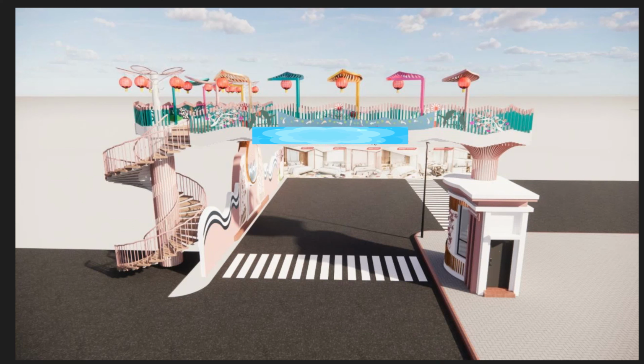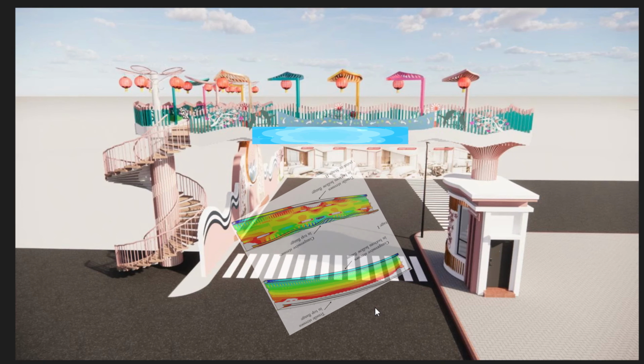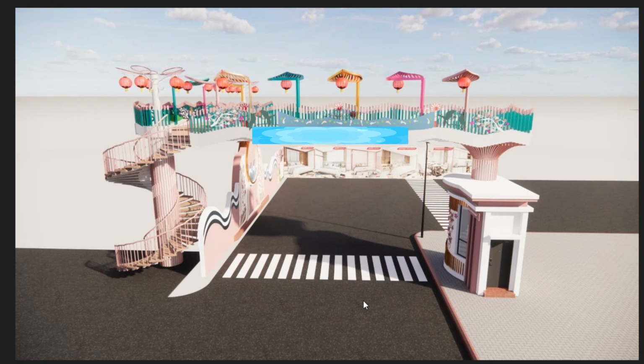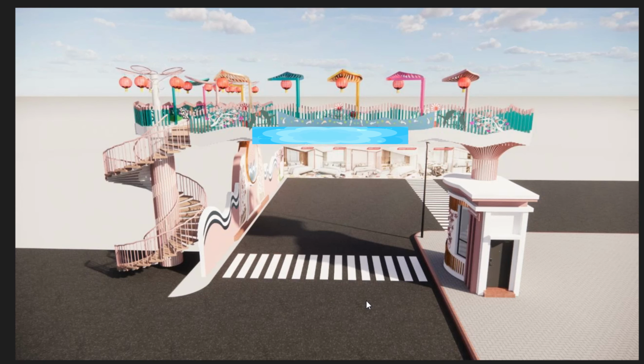3D architectural plan. Now let me ask you one question. How do we design steel composite walkway? What is the design control on the project? The ultimate limit state, the strength of the section, the deflection, or the local buckling or lateral torsional buckling that control this design. Now let's jump into the deep about this tutorial. You will know how to design and how to control and how to check this model.